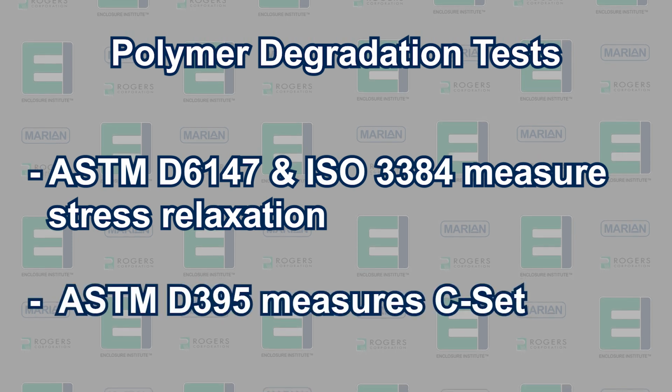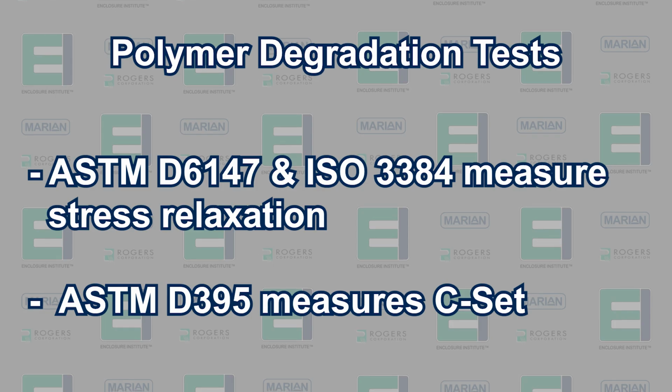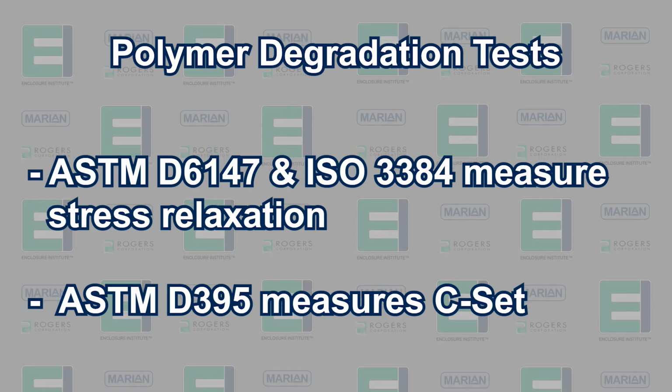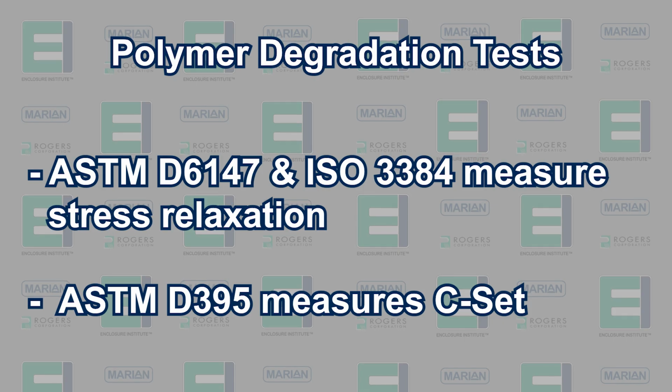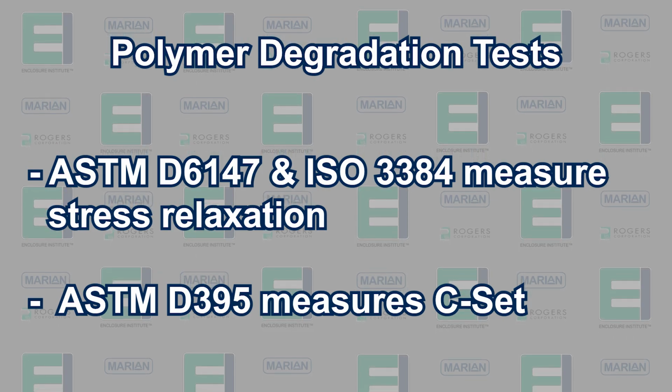And ASTM D395 measures for compression set. As we've explained previously, C-set is the permanent deformation of the foam under load. Compression set is often accelerated at higher temperatures, which can speed up seal degradation in heat-intensive environments like engine compartments or power electronics.